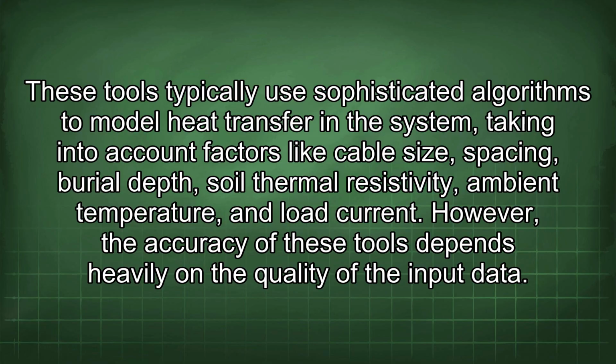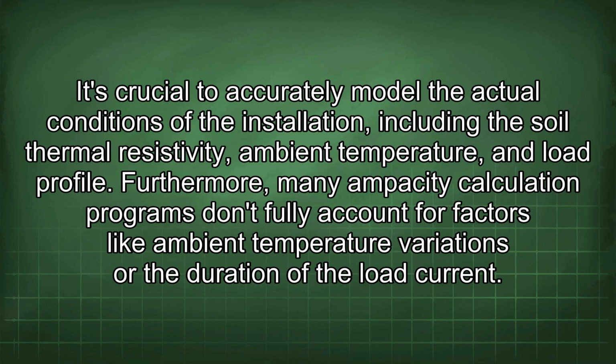However, the accuracy of these tools depends heavily on the quality of the input data. It's crucial to accurately model the actual conditions of the installation, including the soil thermal resistivity, ambient temperature, and load profile. Furthermore, many ampacity calculation programs don't fully account for factors like ambient temperature variations or the duration of the load current.